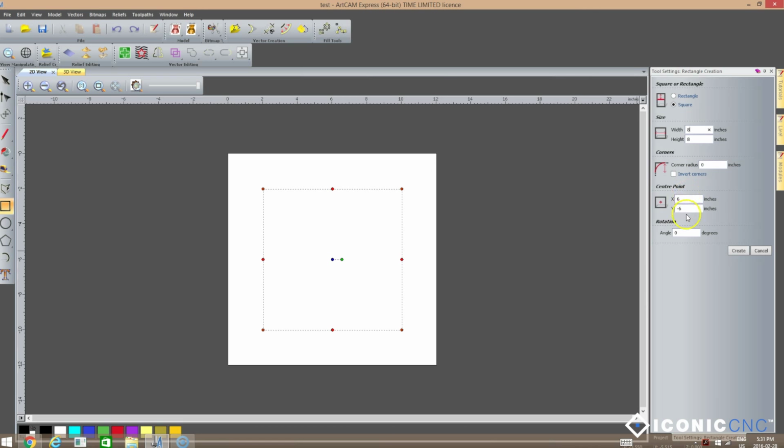And you can see where our center point is set at 6 on the X and minus 6 on the Y. I want to make mention of the fact that you see that the Y is a minus 6, not a plus 6. And I just wanted to help you to understand the reason for that. If you remember, when we set up our materials, we set our origin position at the top left corner at 0, 0. When we do that, what it does is it makes all of the Y coordinates minuses. It's not really a big deal. It's just something to make note of.